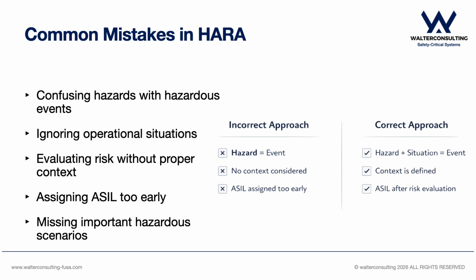Third, evaluating risk without properly defining the scenario. And another very common mistake, assigning ASIL too early. ASIL should only be determined after the full risk assessment. So the key is to follow a structured and complete approach.